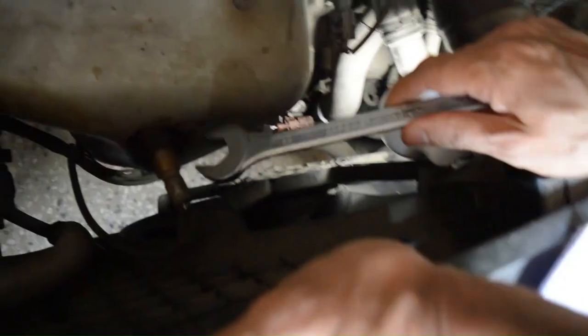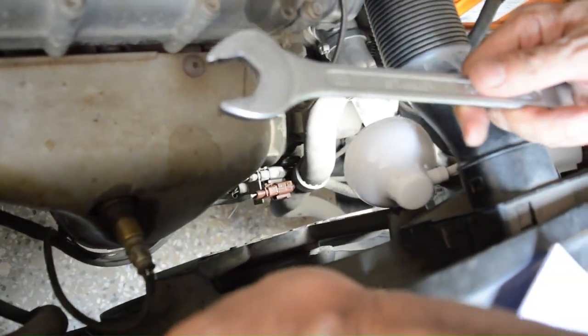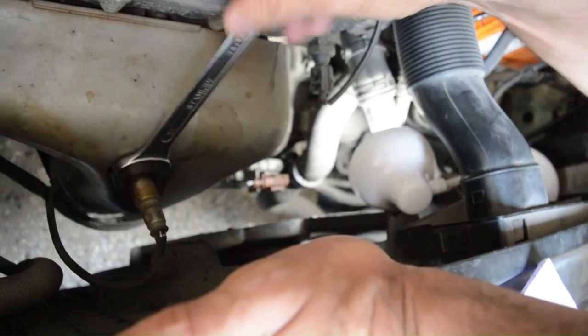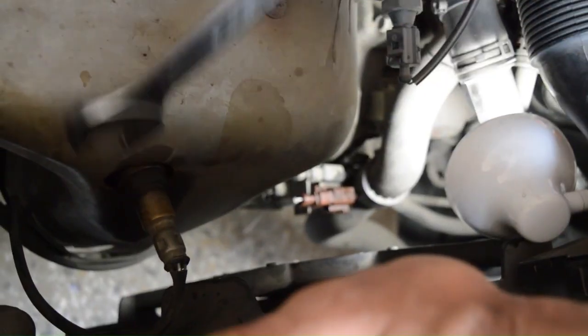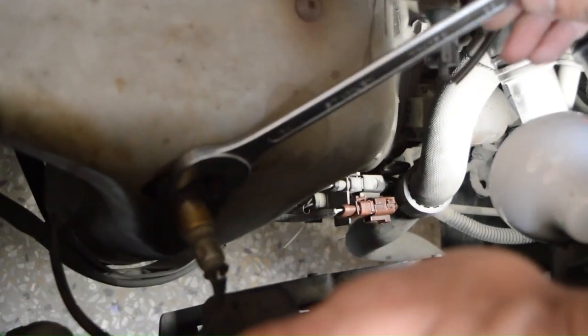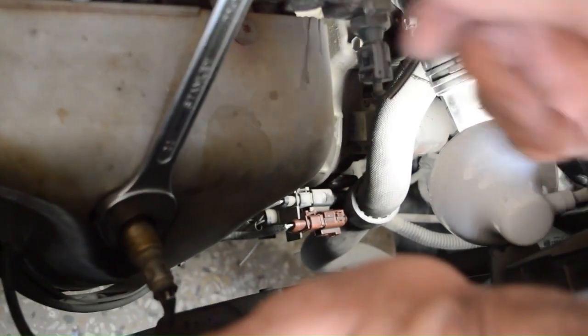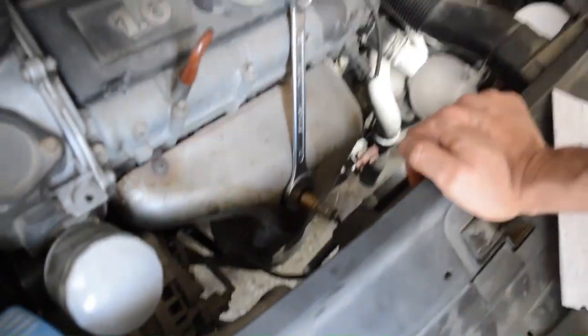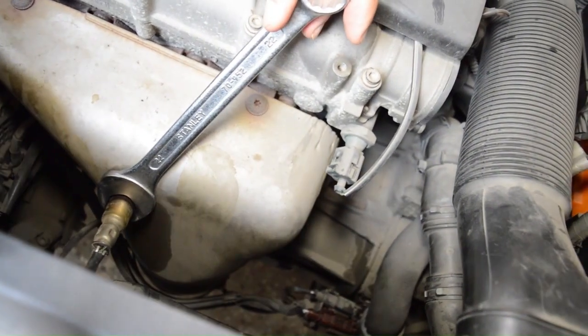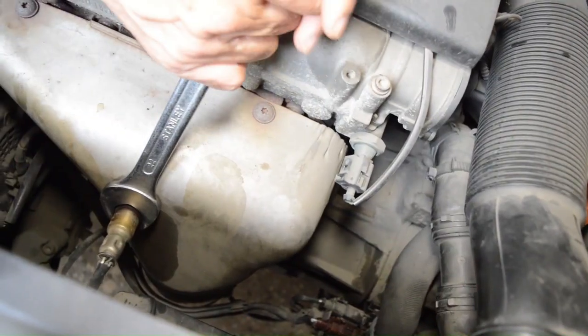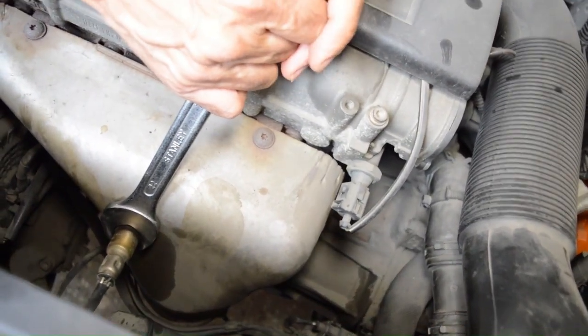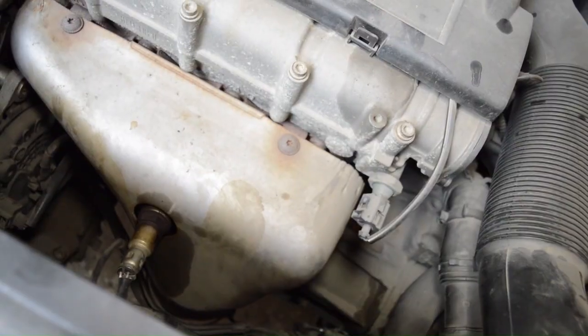So we'll just open it and see if we can clean it. Sensor here, it is a 22 spanner, 22 size. So what we'll do, we'll just put the spanner here, and if we are unable to open it with this spanner, then we'll have to get a special tool, but hopefully I will be able to crank it open. So yeah, so this is it. Pull it, and so that's great.